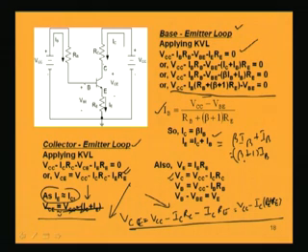And what is the voltage at B? That is VB, VB equal to VCC minus IB RB. Or I can write another expression for VE, which is VB minus VBE. So, all these voltages and currents I can find out in this circuit.